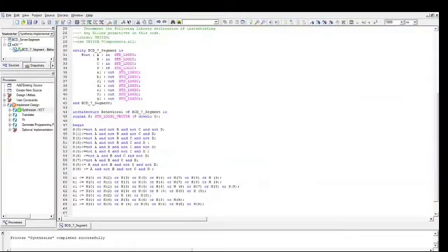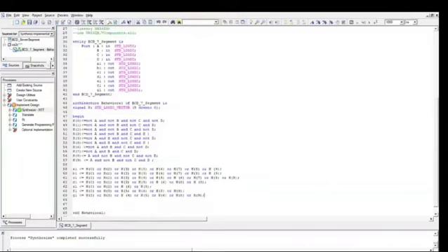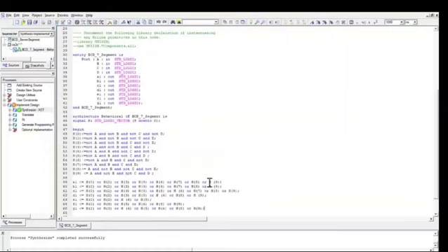After that A1, B1, C1, D1, E1, F1 and G1 outputs are also assigned with the indexes. For example, in A1, if 0th index, 2nd, 3rd, 5th, 6th, 7th, 8th and 9th index is shown, then these segments on the display will light up and others will not light up, which will create a final output. So going further, this is the behavioral code.